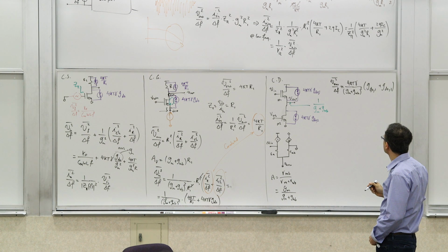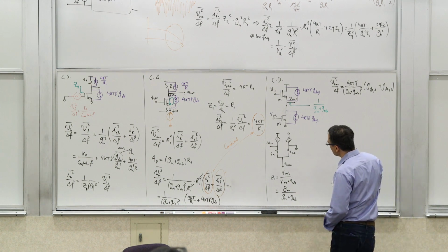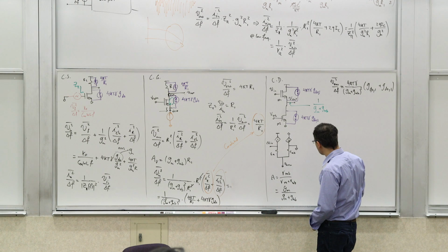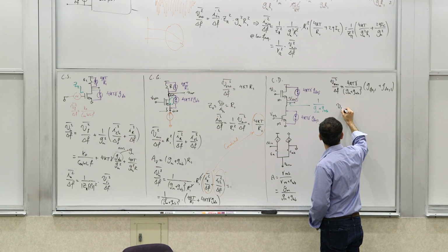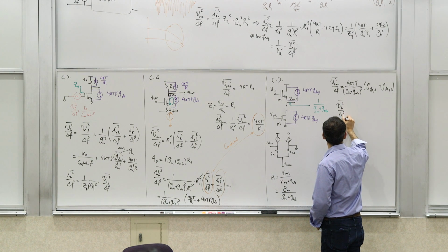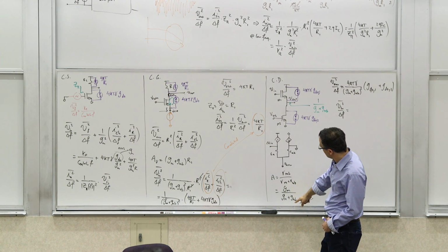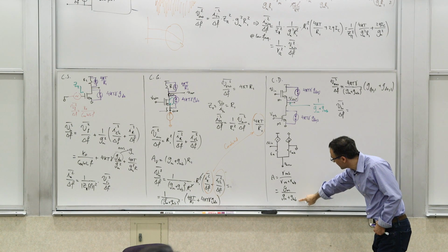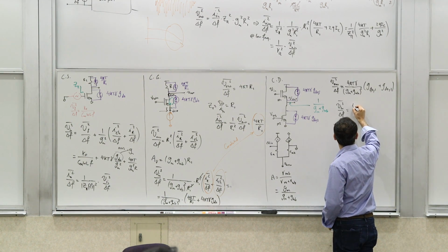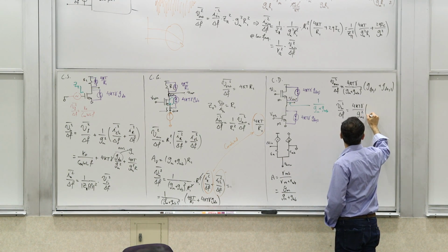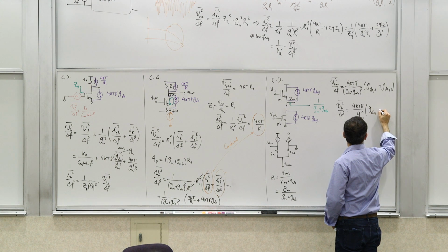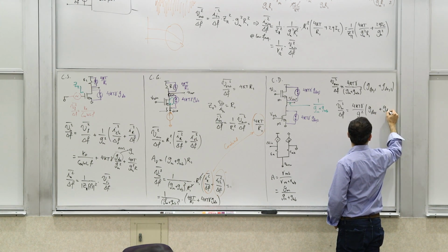And then what's the input referred one? You have to divide it by this gain magnitude squared, which basically gives you Vin² over delta f. So again, this divided by that cancels this term. You get a gm squared. So you get 4kTγ over |gm1| squared times gd01 plus gd02.